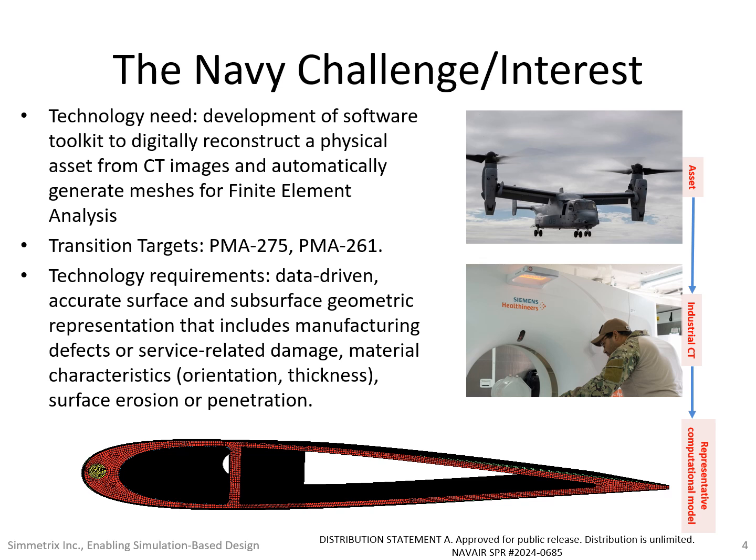The software technology that we developed reconstructs the physical asset using a set of computed tomography images, and therefore captures the features of the measured asset like defect population, operational damage, and material system layout. The product of this technology consists in mesh generation capabilities that generate a finite element mesh representation that can be used to define a computational model and assess performance of the asset.